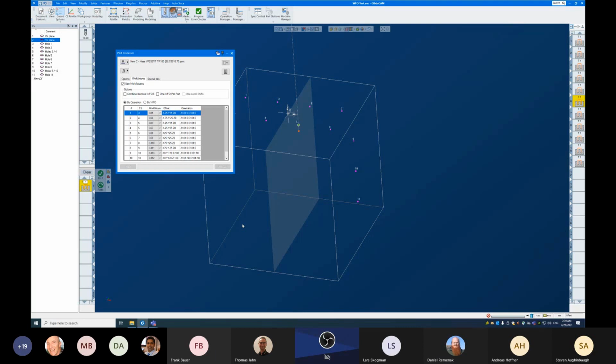correct me please if I'm wrong, but if I use the tool center option and calculate the toolpath with it, and then turn on the tool edge option, I found that it'll change the toolpath immediately, so I do not have to recalculate it. So I could kind of work around it by doing this trick.